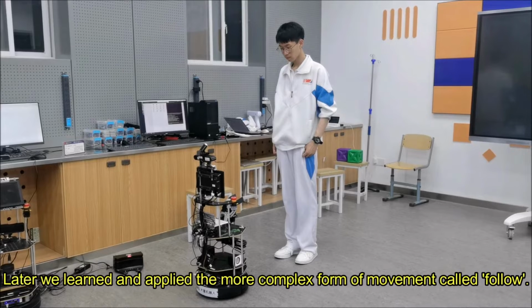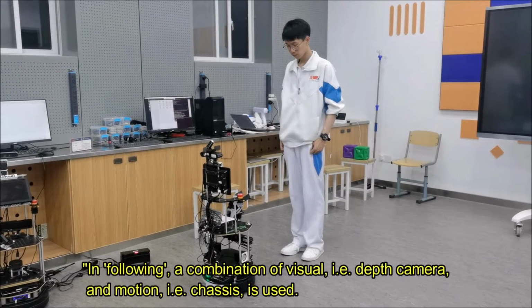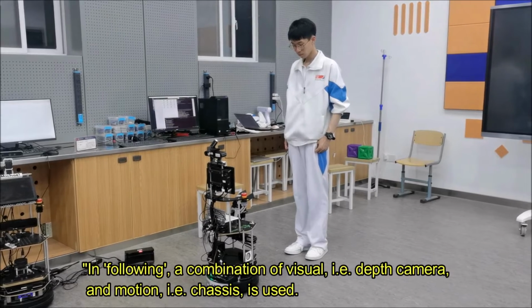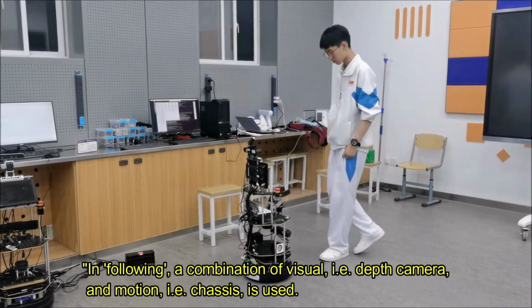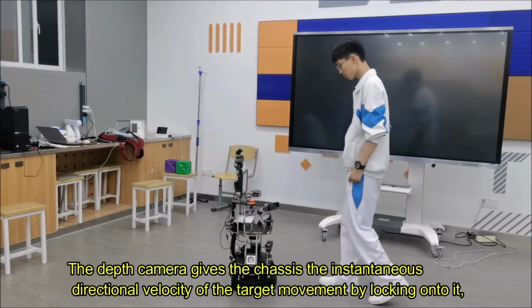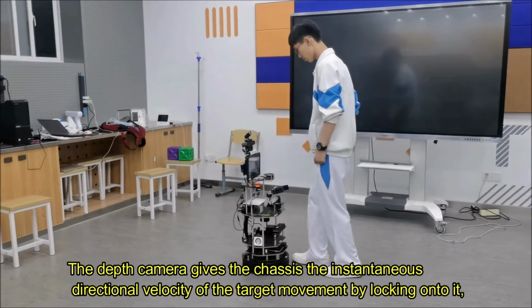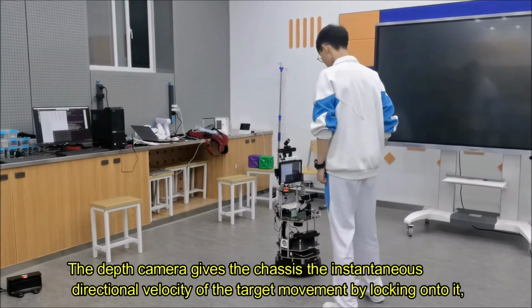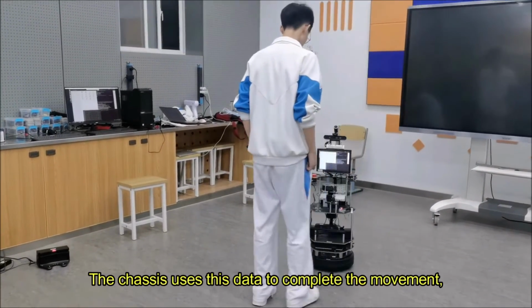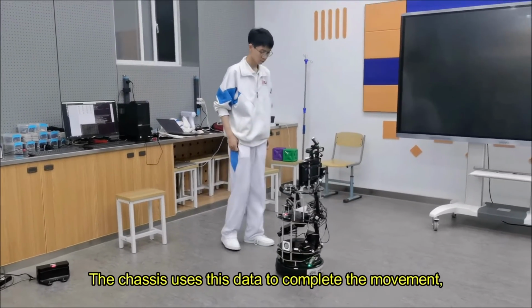Later, we learned and applied a more complex movement called follow. In following, a combination of vision, i.e. the depth camera, and motion, i.e. the chassis, is used. The depth camera gives the chassis the instantaneous directional velocity of the target's movement by looking at it. The chassis uses this data to complete the movement.